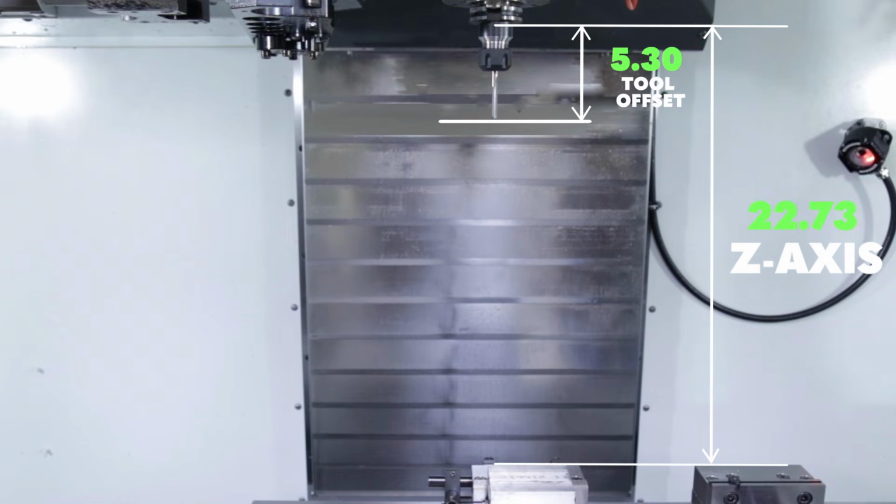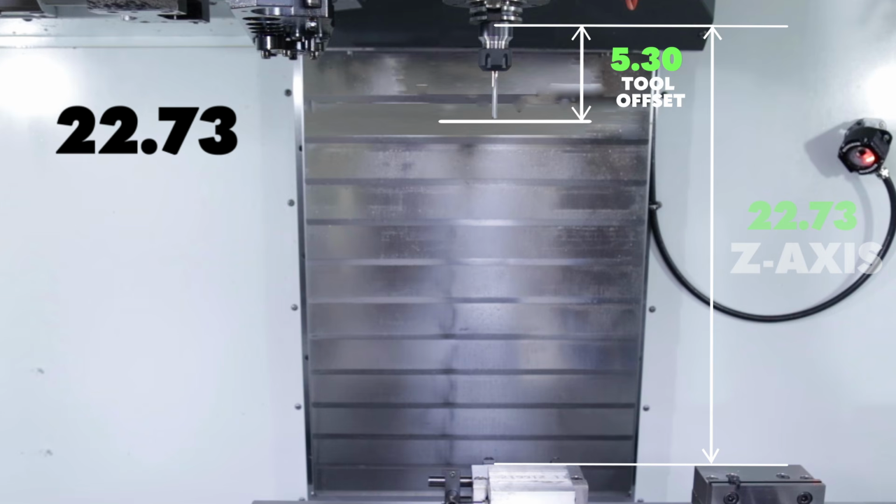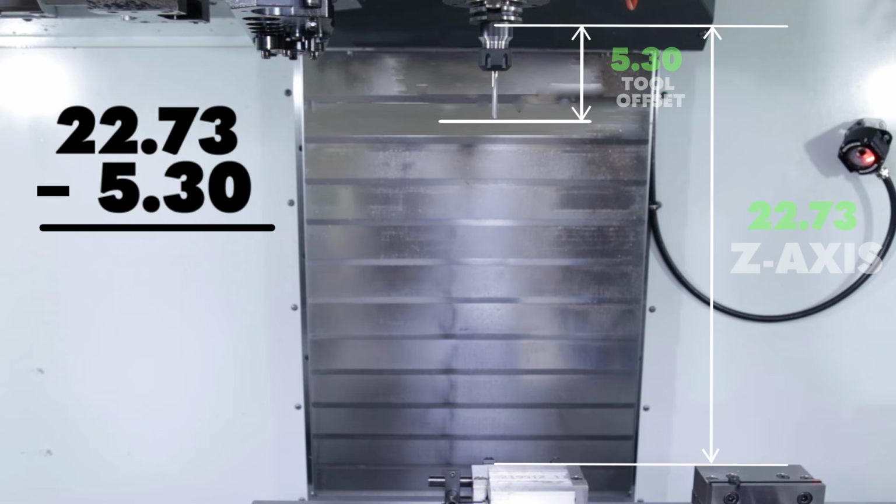So the control will take the 22.73 inch value and subtract the 5.3 inch tool length, and know that the tip of the tool is 17.43 inches above the workpiece at home position. Now the machine knows where everything is located.